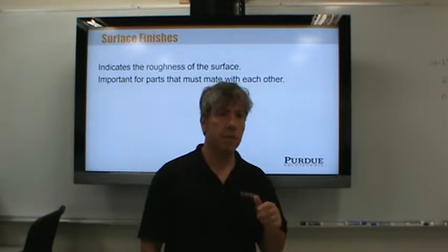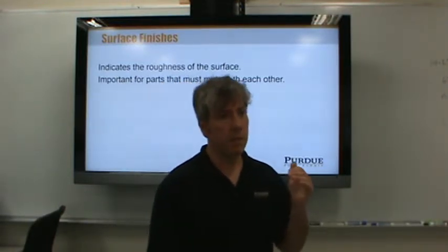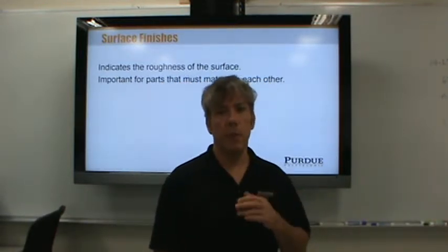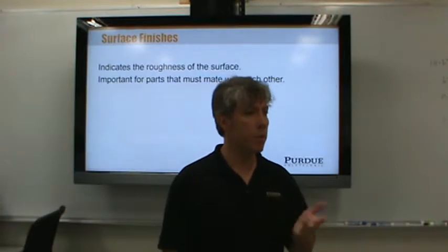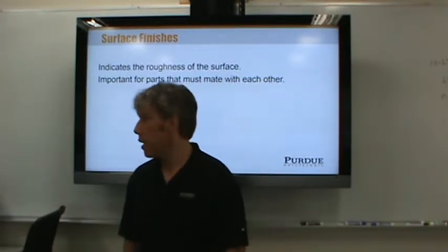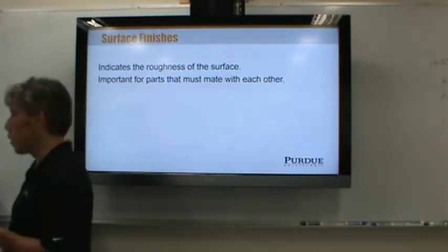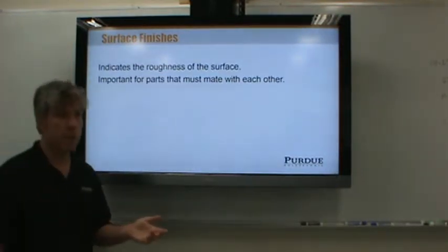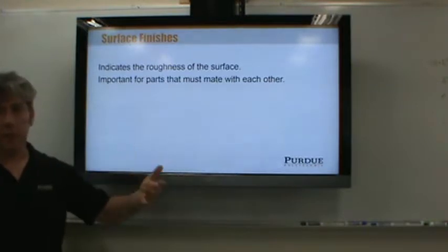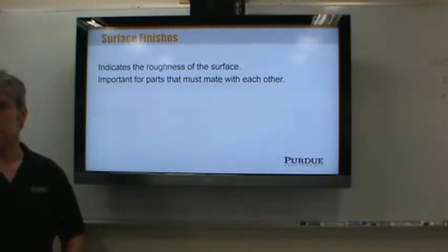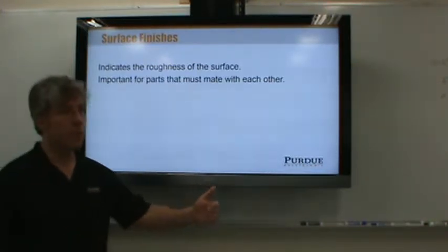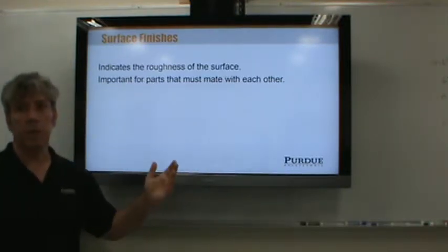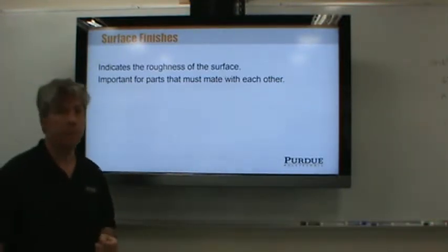So there's a difference in the level of tolerancing and the precision required depending on what the part was, even though both were injection molded parts. Okay? So a lot of times the appropriate level of tolerancing comes from past experience, where we built a lamp and it didn't work, we had to make a tighter tolerance, or hey, we tried loosening up the tolerance on this part, it works fine, had no trouble, so we go with that lower tolerance now.